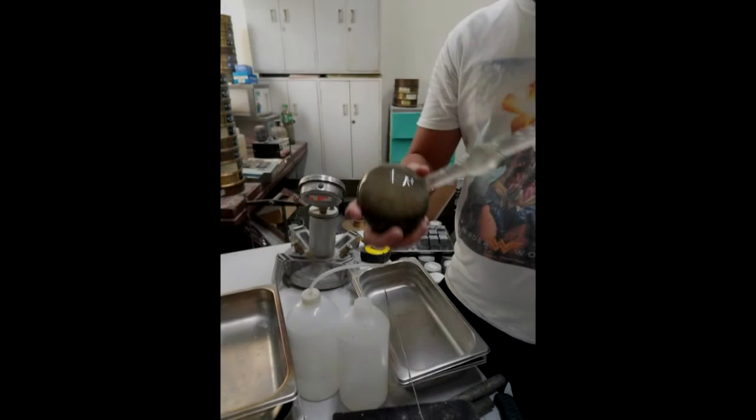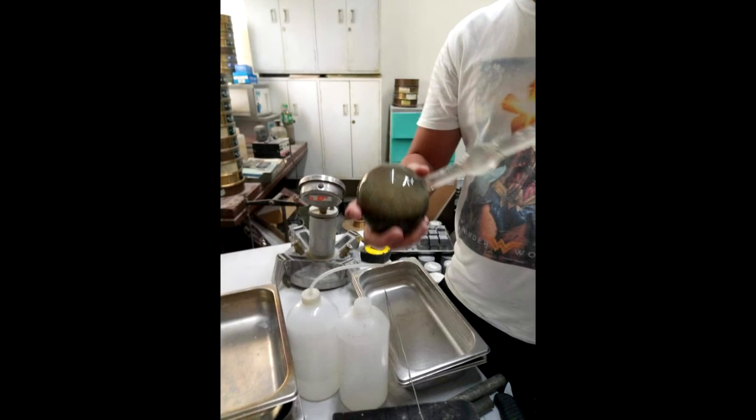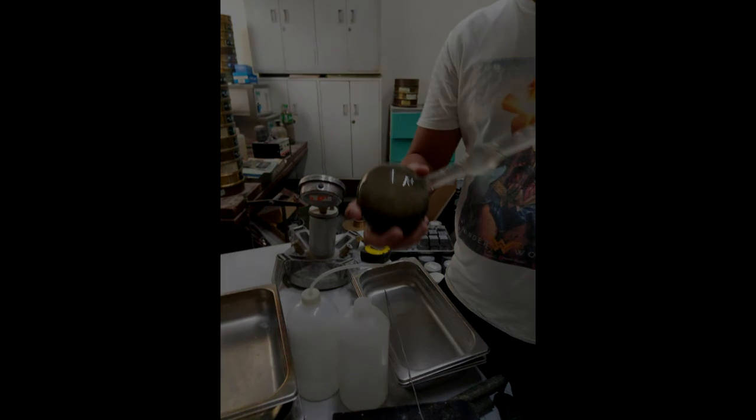There are some values that are established in this experiment. The specific gravity of Portland cement is 3.15. The Portland blast furnace slag and Portland pozzolan cements have a specific gravity of 2.9.